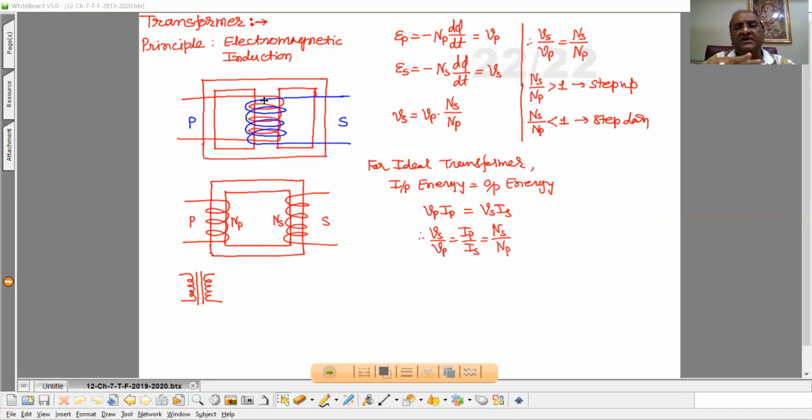When the current is continuously changing direction, positive, negative, positive, negative, half cycles are appearing at the terminal of the primary. So the magnetic field produced is also continuously changing, and therefore magnetization and demagnetization of the core take place. So for that, a hysteresis loop will be formed.